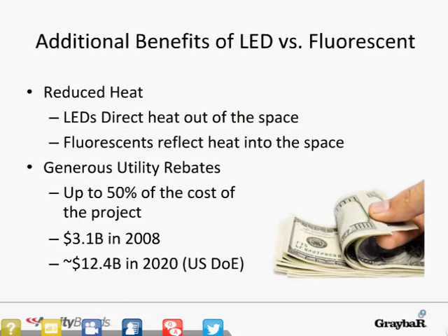Some additional benefits of LED versus fluorescent include reduced heat. Now, we all know this is a major issue in data centers, right? If you can reduce the heat in the space, you also cut down on the cooling costs. LEDs direct their heat out of the space, especially when they're in drop ceilings, right? They direct that heat into the plenum area. Fluorescents direct their heat into the space, so you've got to accommodate for that with your cooling system.